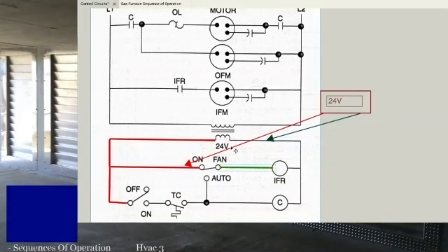So you always want to keep one lead on common, and you'll hear it called the hopscotch method, right? Whatever you do, you keep your black lead placed on common, and then you test everything else using your red lead, with your black lead always on common, to make sure you're always reading voltage. Unless you've gotten really good and you're really proficient at troubleshooting control circuits, you don't want to test right across a switch. Okay, because testing right across a switch will give you 0 volts, right? If you're trying to make sure you got voltage, right?